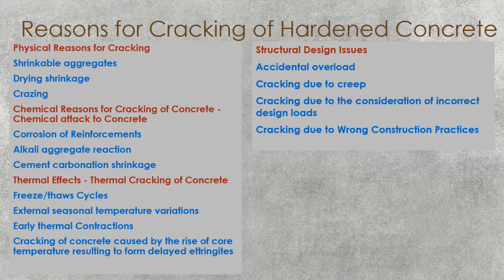Early thermal contractions. Early thermal contraction also would occur in the concrete, but if you have designed it properly or provided adequate reinforcement for such movements, you could avoid this type of crack.